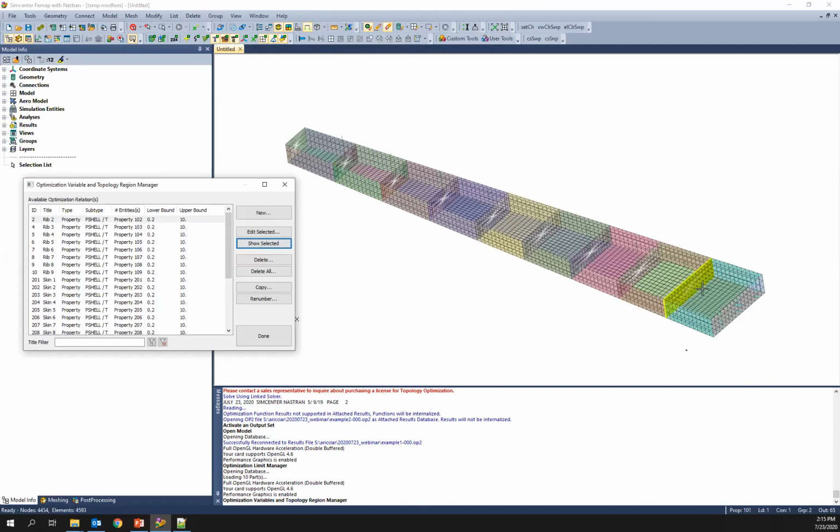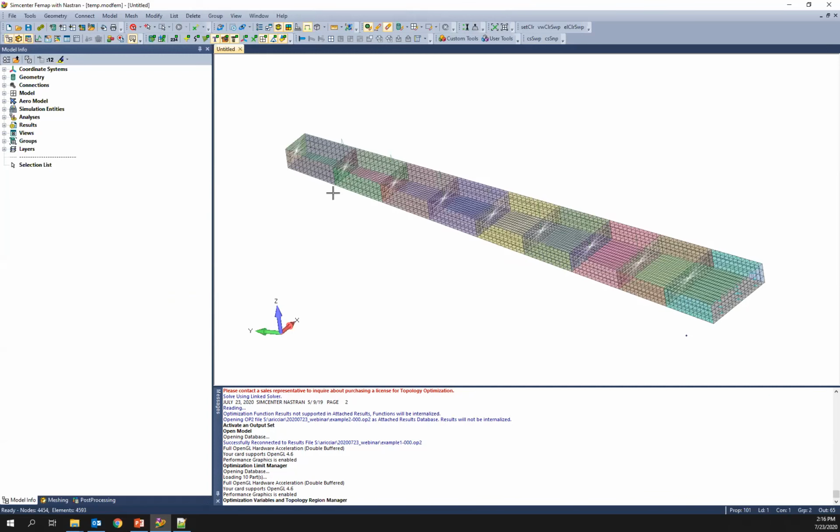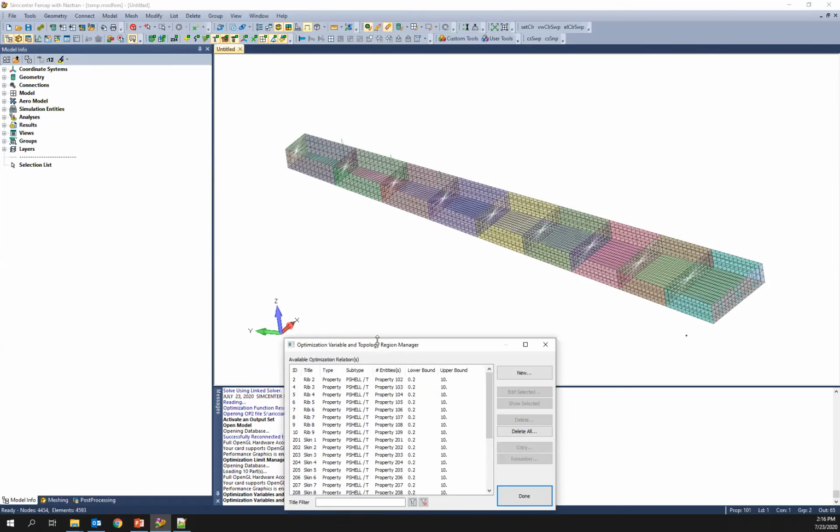This design variable is corresponding to this rib thickness, and you just go along the span. There are independent design variables and regions corresponding to the different ribs. The skin, top and bottom, there's one design variable controlling that. So there's span-wise variation allowed. There are discrete values for these panels, and design variables are going to adjust these thicknesses to achieve our design. So there's quite a few set up there. I think there's 26 total.